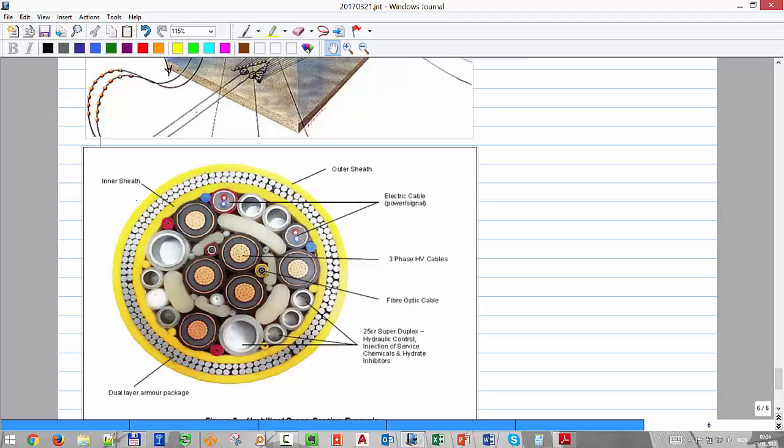Then you have these pipes that carry the hydraulic fluid. Remember that all of these big valves, like the master valve, wing valve, are moved with fluid. Okay, and also the subsurface safety valve, high pressure fluid. So that fluid has to go at high pressure. And remember also we have a low pressure. All of these pistons, when we move them, okay, like for example you have here the actuator. That I think we didn't discuss, but we have our gate valve.